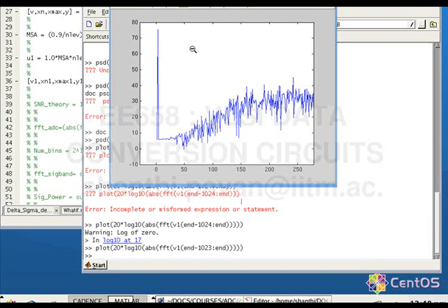Okay, so here if you observe the trend, you can see that the shaped noise is reducing, but beyond a certain point it just simply becomes flat, because the shaped noise is supposed to have gone down like this, but then there is discontinuity and that just fills up all the lower bins. You follow? So that is the problem with using a rectangular window in delta sigma modulator measurements.